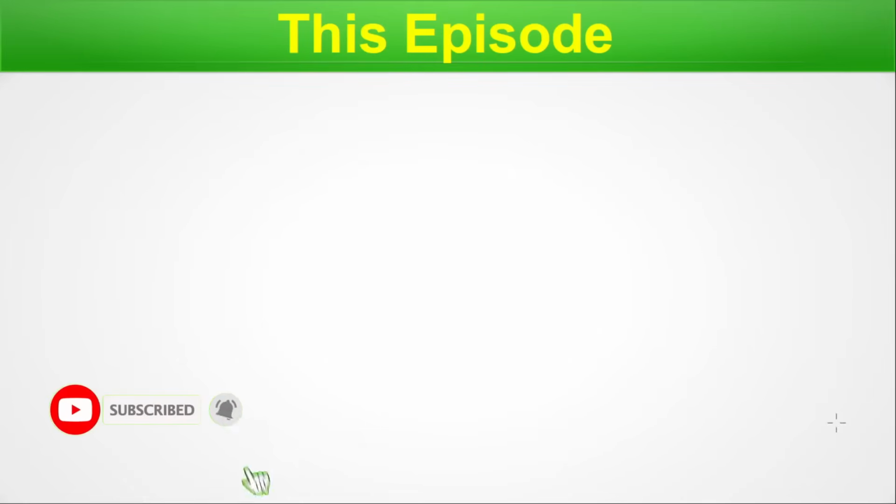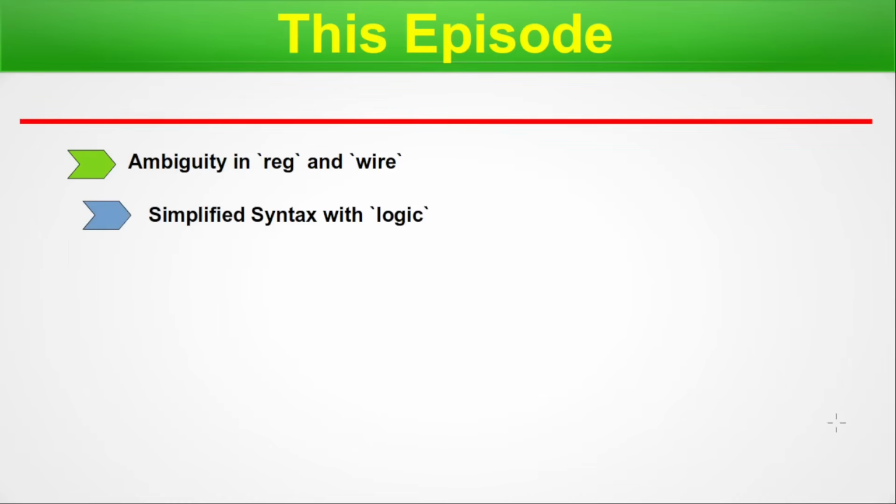So here is the menu for today. In this episode, we'll discuss the points: ambiguity in reg and wire that was in Verilog; simplified syntax with logic, which is a new entry in SystemVerilog; bit for two-state logic, which is also a new entry in SystemVerilog.